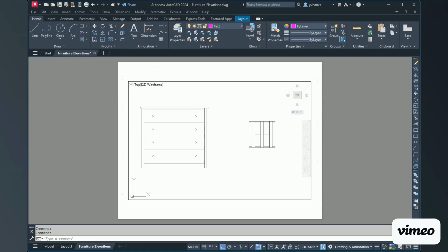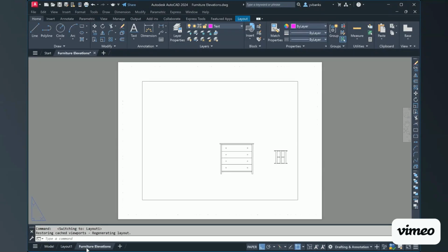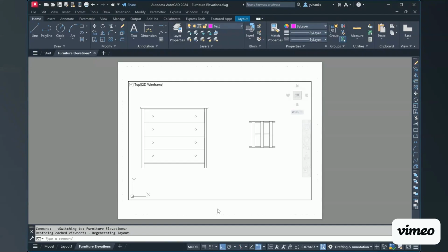Getting started here, I am currently in the paper space, but just to backtrack a little bit, remember we are drawing everything in our model space, and then from there, when we're ready to print or add our text, we're going to do that in our paper space. Everything created in paper space is going to be created at a 1-to-1 scale. So when you need to put in a height of your text or the scale of your text, you're going to type that in manually. In this particular example, there's no need to set up any annotation prior to working in this paper space.